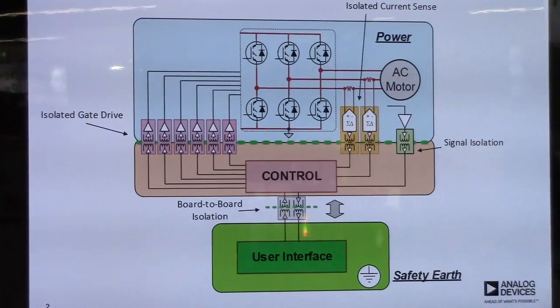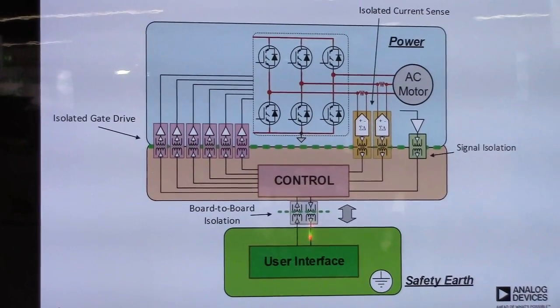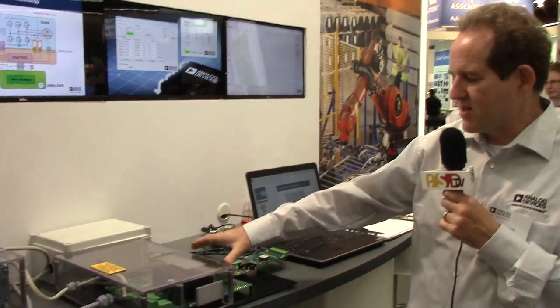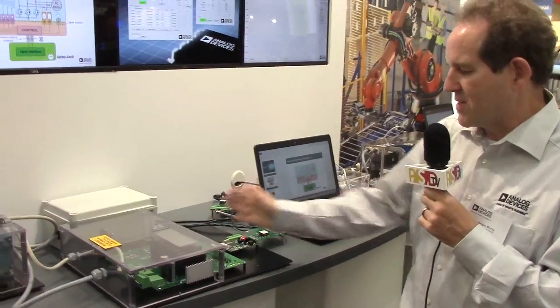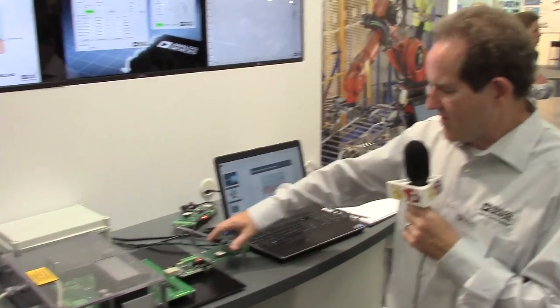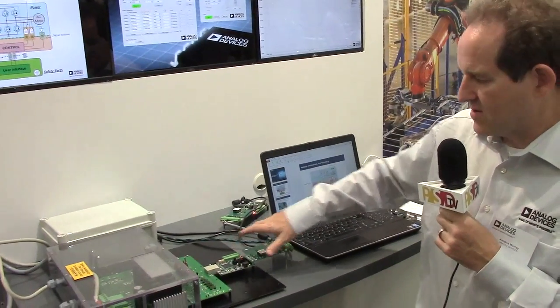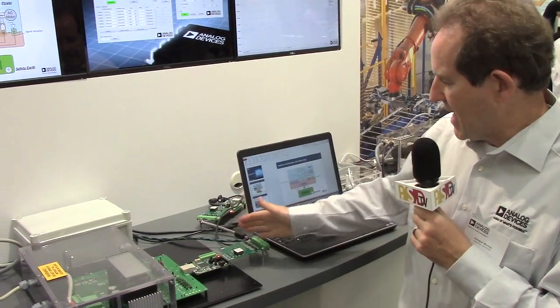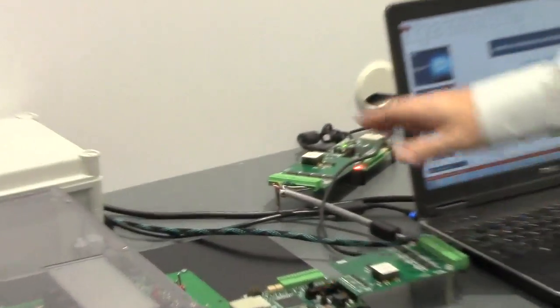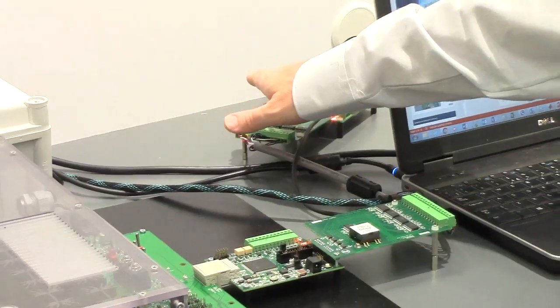Now this is something we're seeing more and more in drive systems, because customers would like to shrink down the isolation components and have just functional isolation on the power board so they can make a very small inverter. And now they will have a control processor that's doing motor control and have either a backplane or a connector to another board that's doing the communication interface.